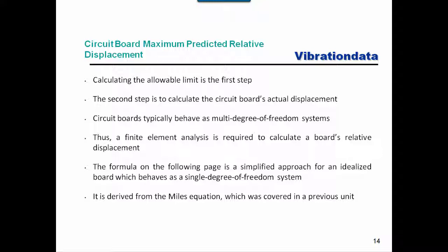And we're also going to talk about a reintroduced Miles equation, which is just a quick hand calculation method for determining the response of a single degree of freedom system to a PSD base input. Now, some of you that are particularly astute are saying, hey, wait a minute, didn't you a number of webinars ago teach us a better-than-Miles method that sometimes you refer to as the general method? And the answer is yes, and I think as a bonus I'll include that method here at the end of this presentation. But just to be consistent with Steinberg, we're going to use Miles' equation.